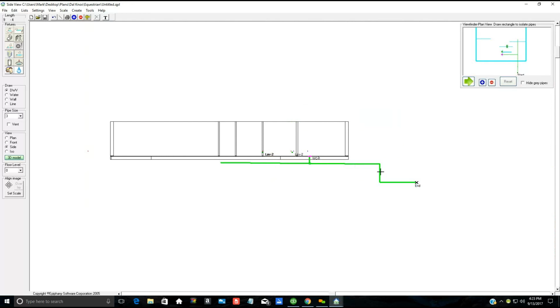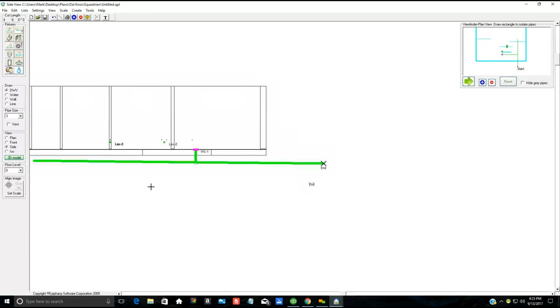But the inches from finished floor, let's say that 24 inches, is that to bottom of pipe? Oh, okay. Let's just check. We can check that pretty easy. Let me just delete that one. Because let's say the civil drawings already have the invert for the sewer main coming up, so we know where we have to get to.